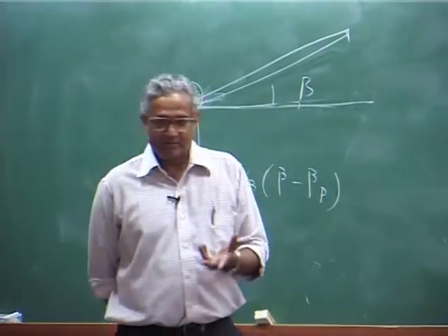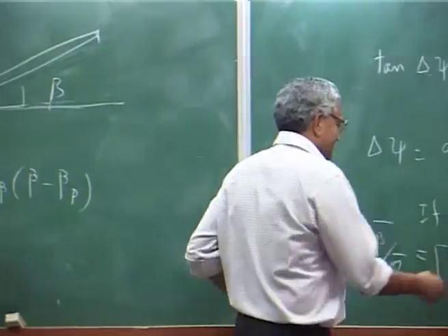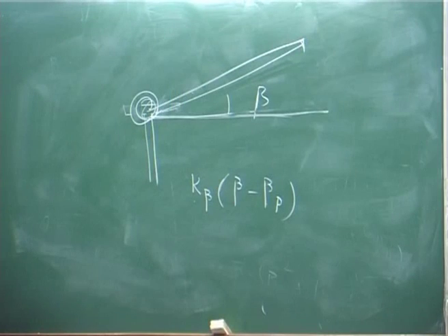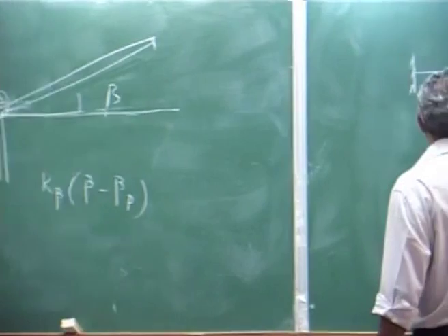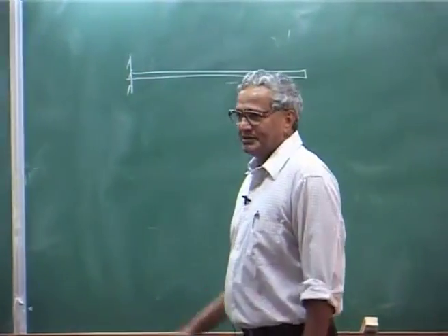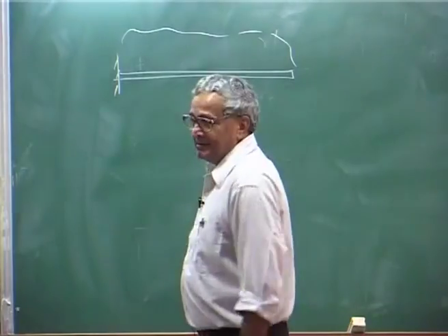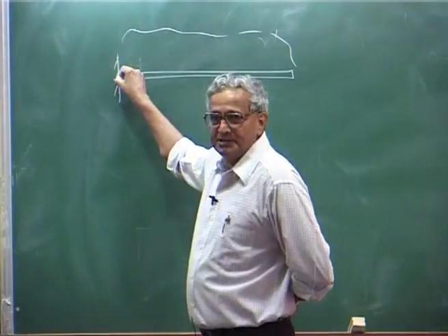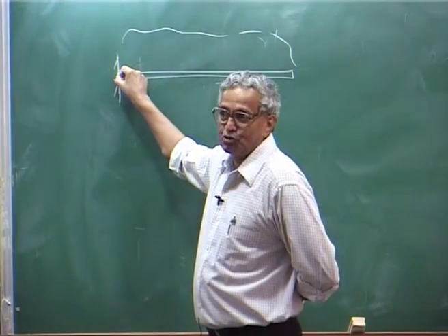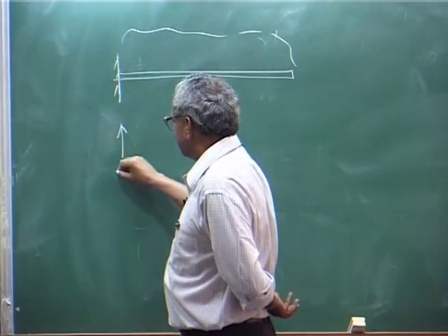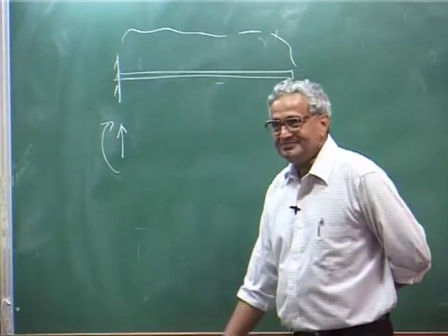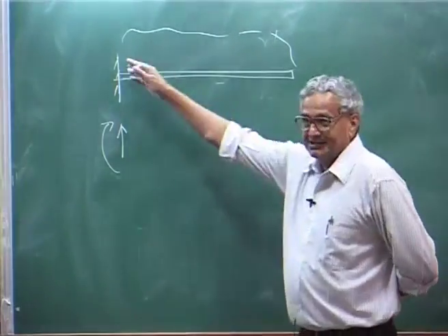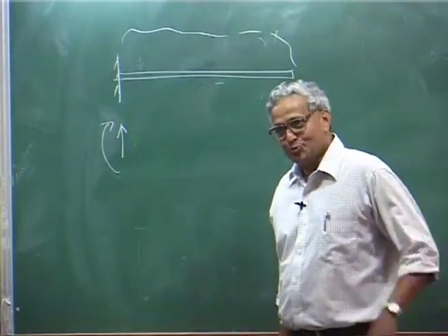Okay. I am just throwing it to you to think about. I am deviating a little bit. Take a cantilever beam with some loading that you have learned. I want to know the bending moment and shear force at the root. How do you do it? You integrate the loads, you will get that. That is one way.